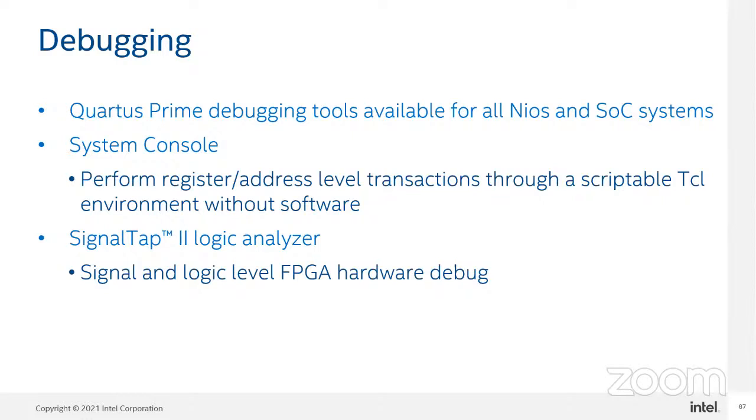You can recollect that yesterday we did a memory design where we created a memory initialization file, but then we stopped there. Today, what I'm going to show you is, first we are going to simulate the design and check the output in ModelSim, but we should also implement the design onto the board. After implementing the design onto the board, we are going to use the on-chip debugger and see whether it is providing the same output on the board also. That is the kind of experiment we are going to see.